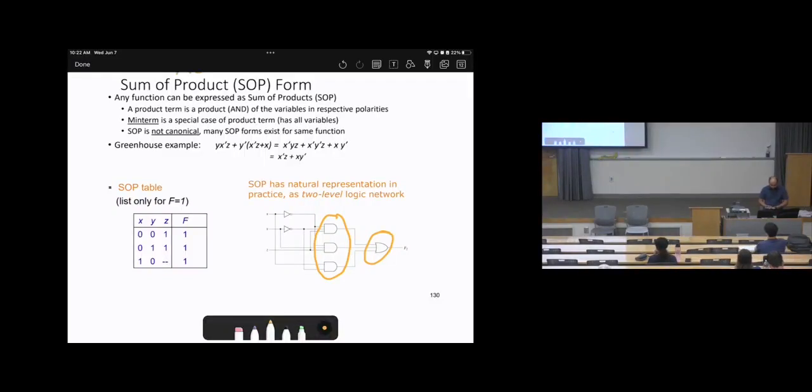So when you manipulate this function using the AND terms, we can get AND and OR gates to represent this. So sum of products form can be in two representations. We have canonical form, and we have other simple forms. So sum of products is a general name, and canonical form is part of it. How can we understand whether this is a canonical form or not?